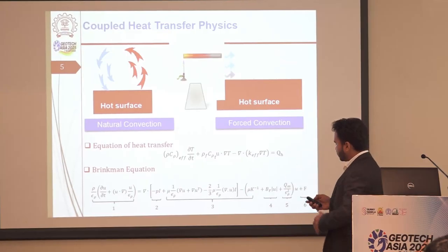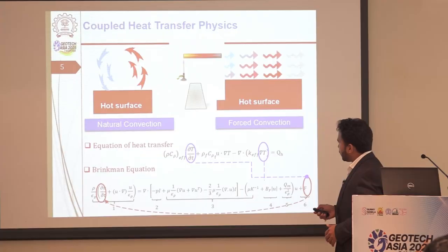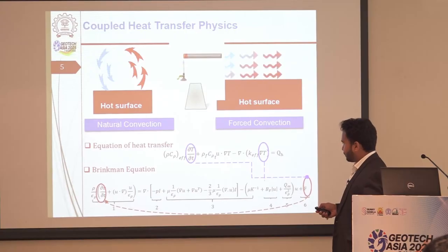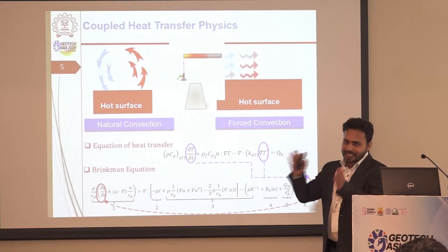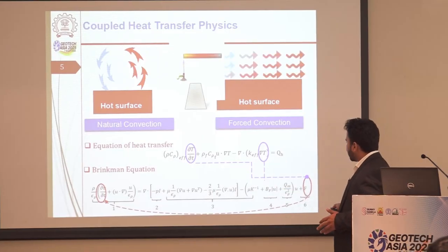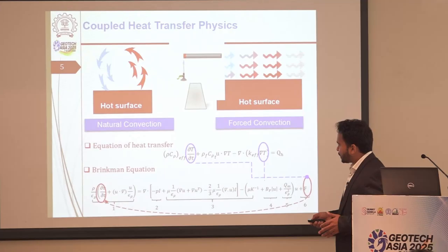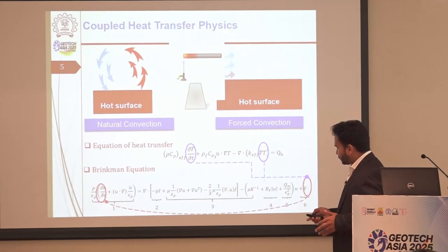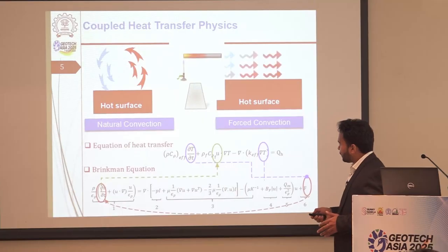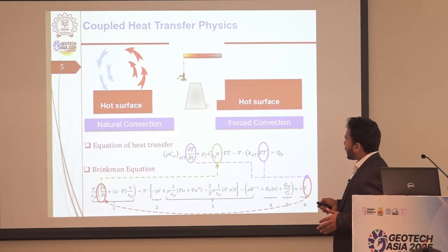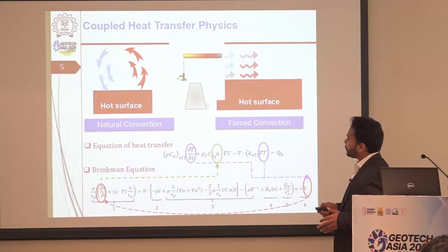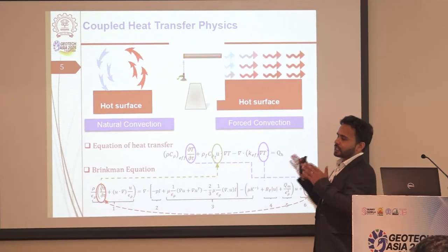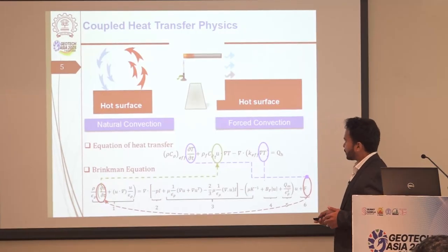thermal and hydraulic both. So here is a time dependent change in the temperature, del T over del t. And because we have a thermal gradient here, the density of the pore fluid changes in the medium. And that density driven flow creates a volume force in the fluid, and that triggers a velocity here. Once this velocity is triggered, this velocity will activate this component. So by two-way coupling, the heat transfer and fluid flow both influence each other, and this process becomes, you can say, a highly non-linear process.